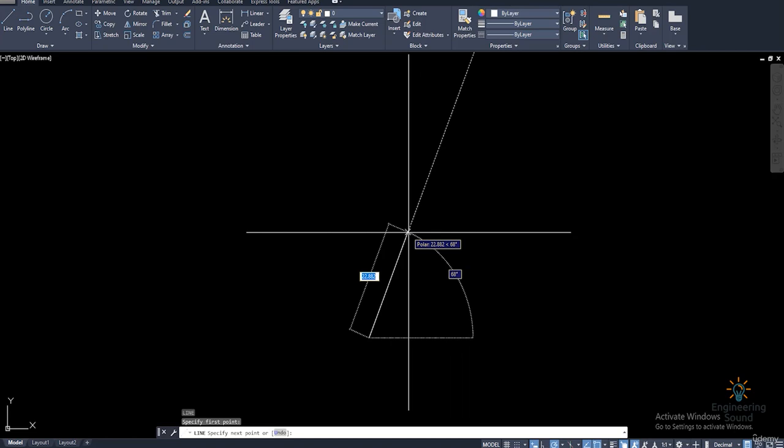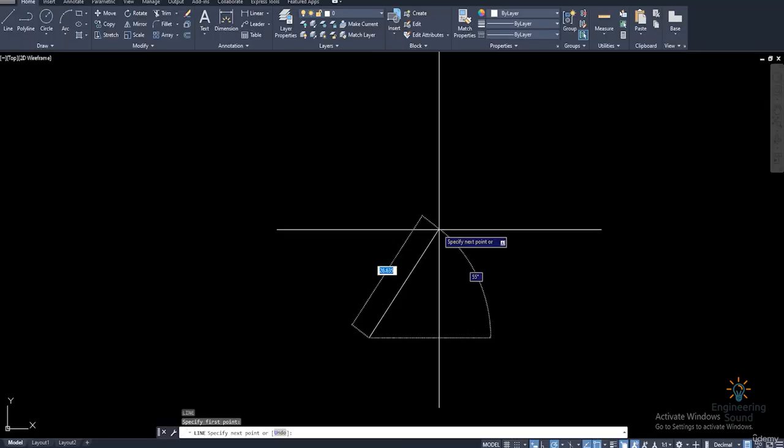So when you draw the line, you will see this tracking line, and you will see the degree from here, showing how much your interval is. You will see this tracking line once you start to draw, because it also goes at 1, 2, 3. But if you start from 0, this tracking line will provide the angles as per your required interval.